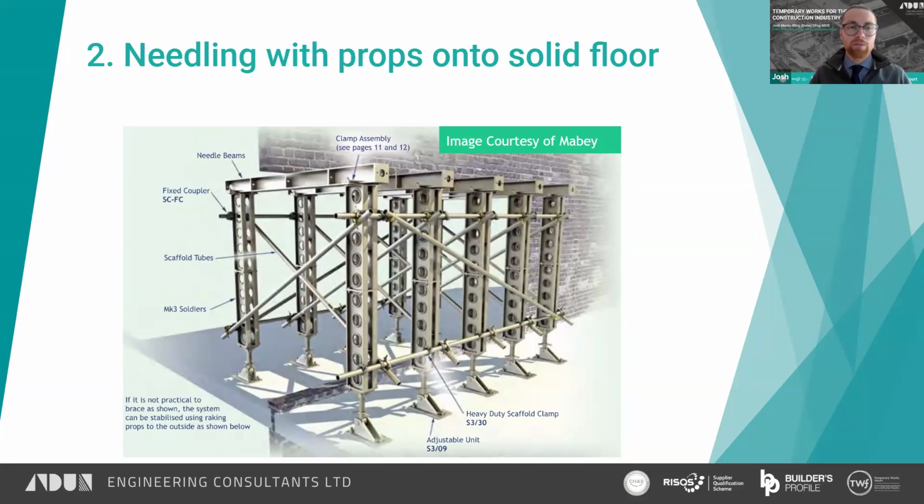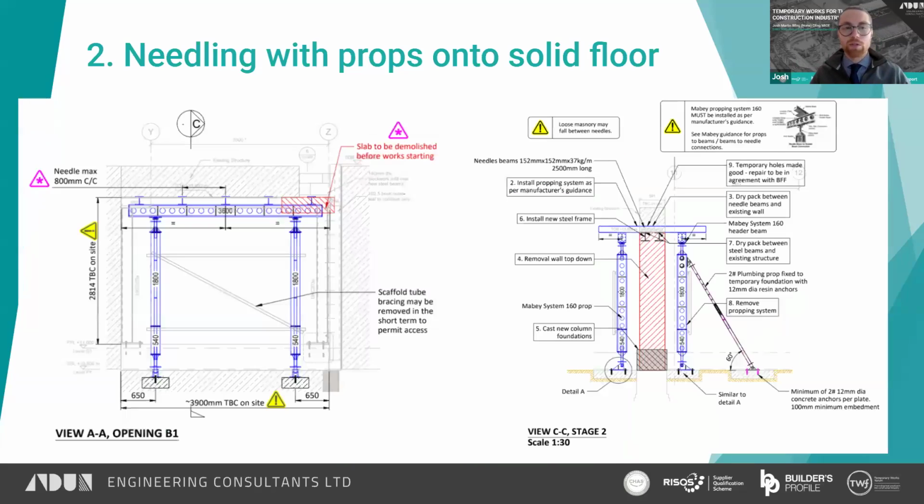And the load follows down the wall through the needles and then down the props and into the ground. We've got some horizontal bracing there just to provide stability, to make sure that the needles don't act as a sway frame and move. That's the general concept.